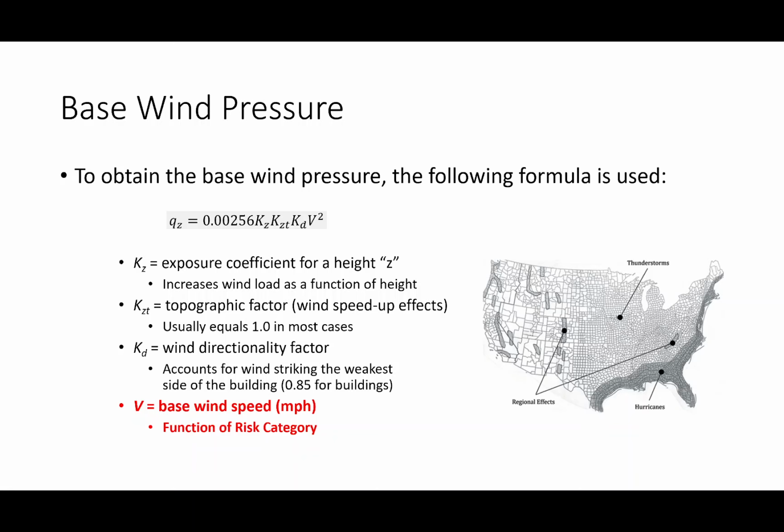Tornadoes are a little bit of a specialty design inside structural engineering. The idea behind a tornado design is, let's say you're designing a building, you might design the building for regular old wind loads, but there is a certain portion of the building that you design for increased loads, and that's your tornado shelter if something goes wrong, if you have a major tornado event.